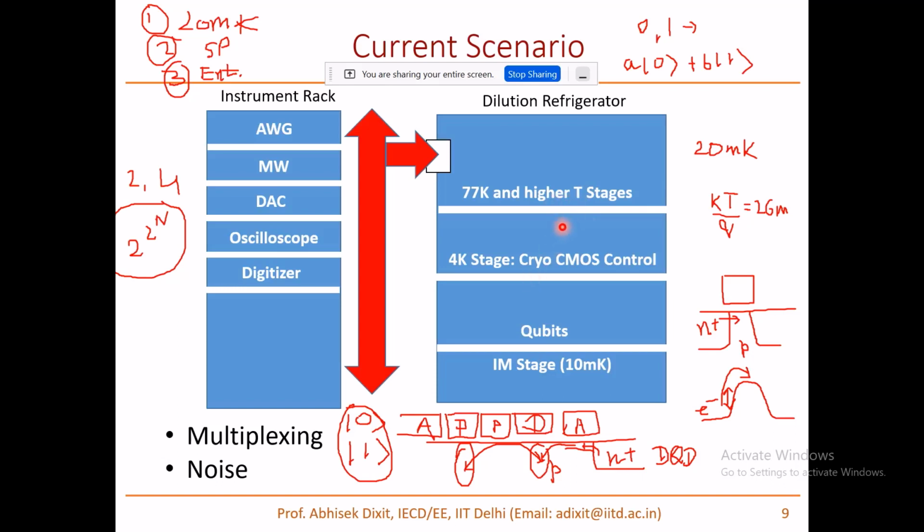What is very important for us is to make sure that not too many wires are here, right? If I say that one qubit requires 10 connections, then to measure 2 qubits at the same time, I require 20 connections. If I want to measure 4 qubits at the same time, I require 40 connections. 40 connections is a lot of wires whose other end is connected somewhere at room temperature. It is going to bring in a lot of heat because these are metals, or good conductors. So that's not possible. So what we do is we bring in few wires and we do multiplexing.